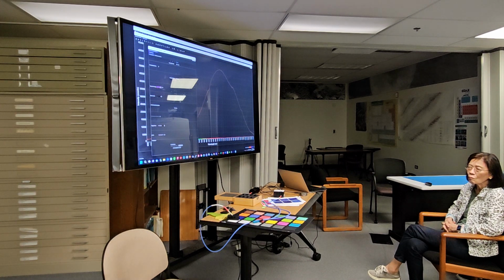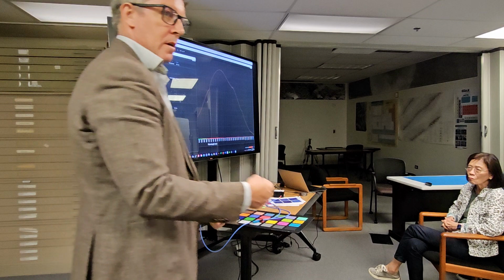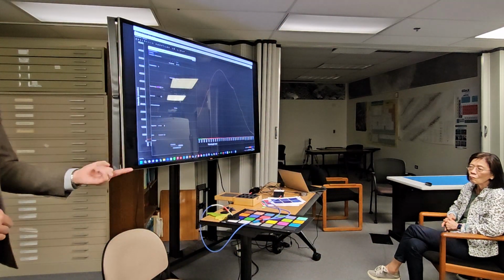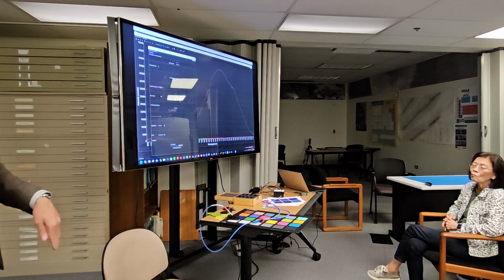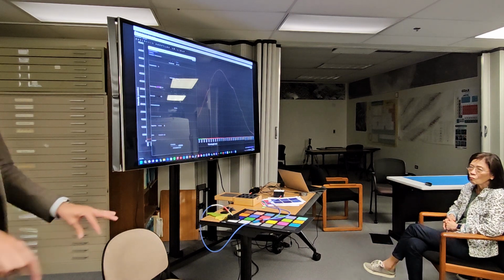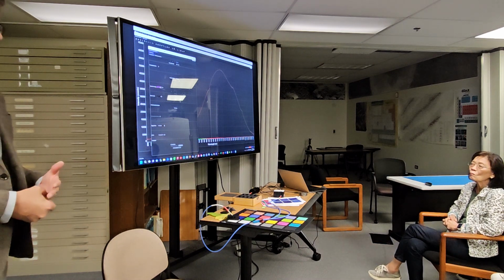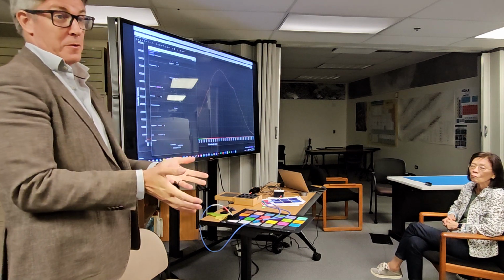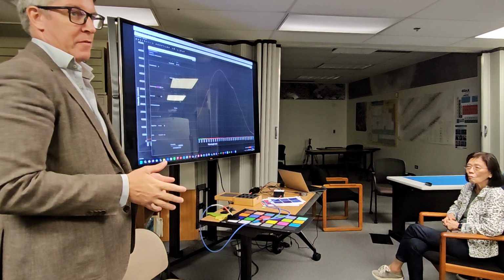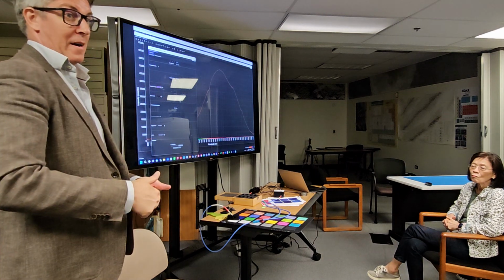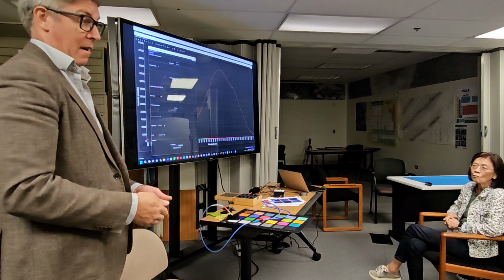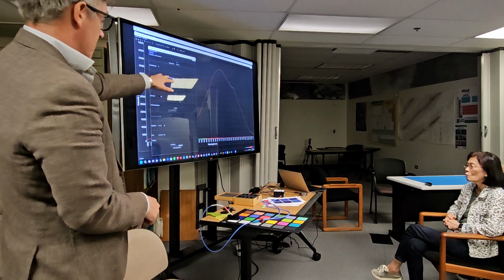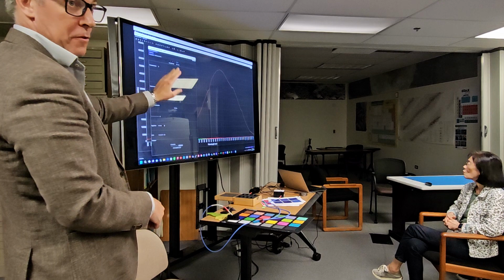And because I'm moving in this direction, it's kind of a rolling average. What I can do in that case is take 10 measurements, add them, divide by 10 to produce an average for each strip of the ground. And that's a technique called time delay and integration, or it's one way of doing it. So it's a way of boosting your signal by increasing the apparent time you're looking at each patch of the ground. And it achieves something kind of similar, it just beats down some noise for you.